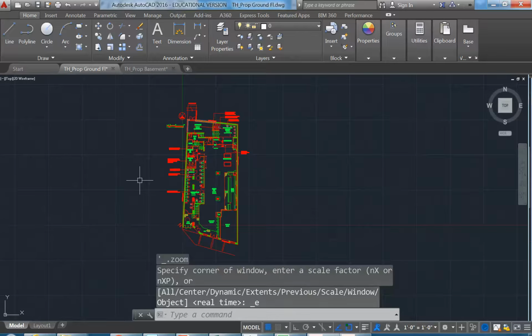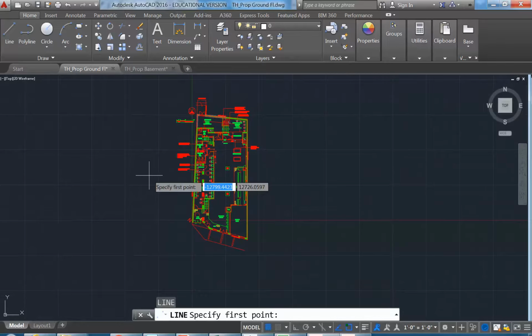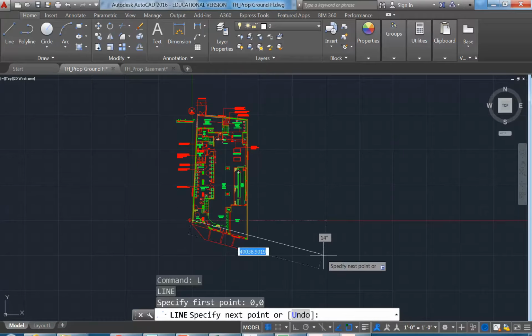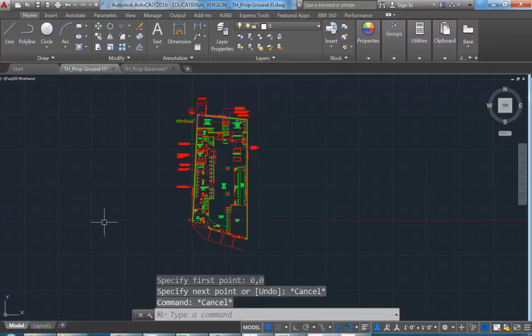And there's a setting that controls that, but you can always find the origin if it's not clear. You can tell from the grid lines on the screen, but just try drawing a line from 0,0 if you're not sure, and there you can see that the origin is basically where the red line and the green line intersect. Just a bit unclear sometimes.